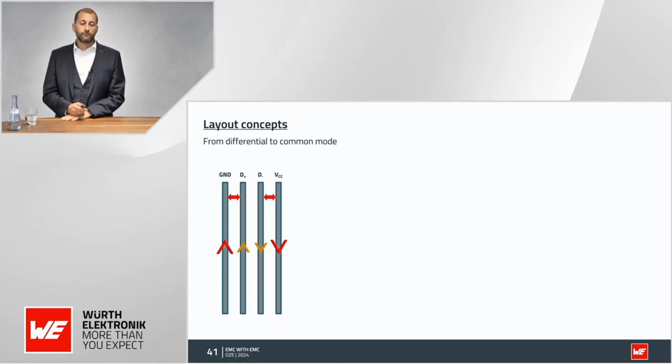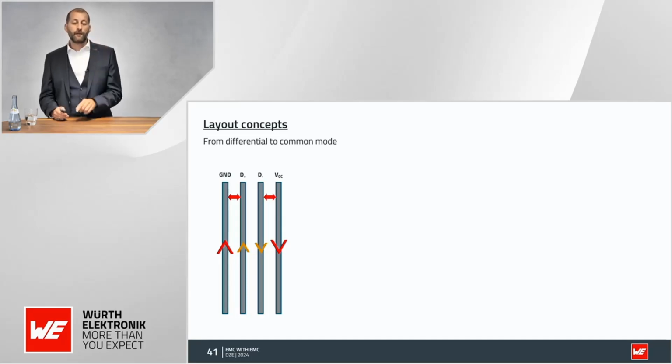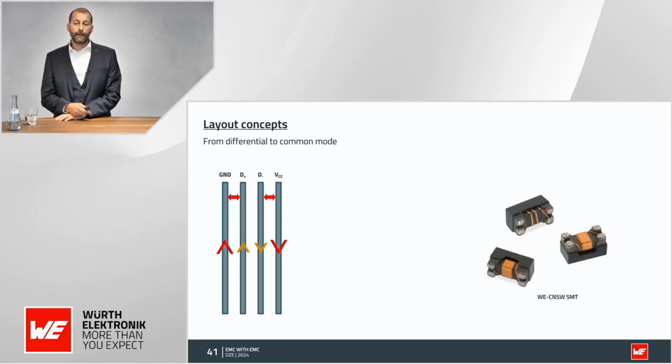If we would now apply, I don't know, an SMD ferrite, it would, of course, reduce the noise, but sometimes it will also affect your signal integrity, meaning the square wave is not ideal anymore and it's becoming rounded a lot. So what could you do? Well, you could use a common mode choke. The problem with a common mode choke is they are not really working with differential mode noises. So we have to somehow transfer from a differential mode to a common mode.